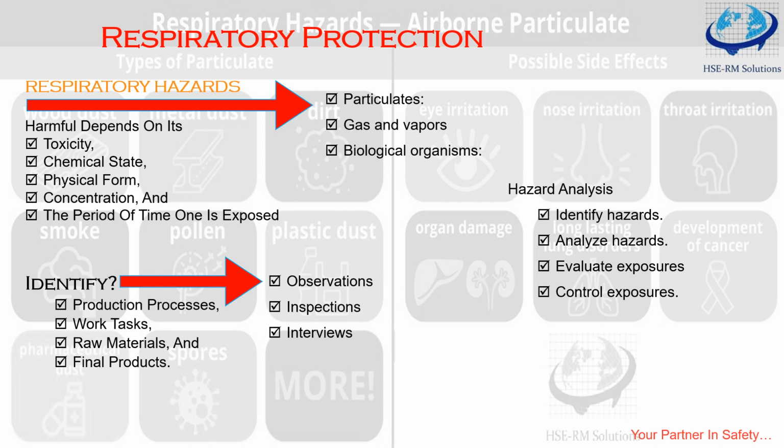Now let's add one more part to the hazards that we are discussing, and that is an oxygen-deficient atmosphere, correct, or an oxygen-enriched atmosphere. Now normal air has an oxygen concentration of 20.8% of volume. So there is a misconception, like people say normal air concentration is 19.5. No, it is not normal air.